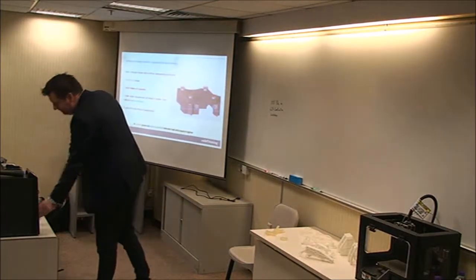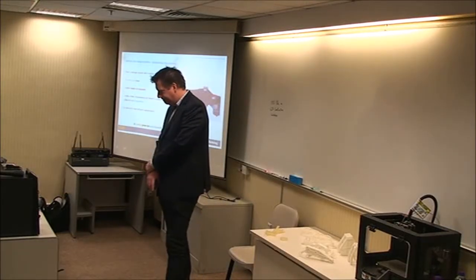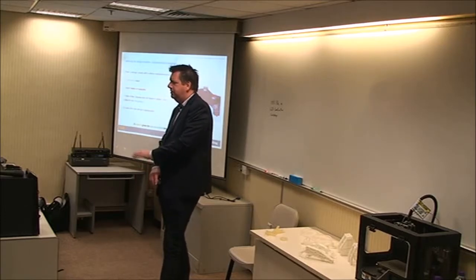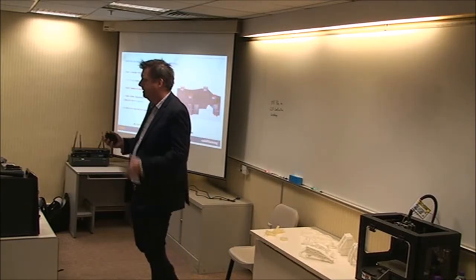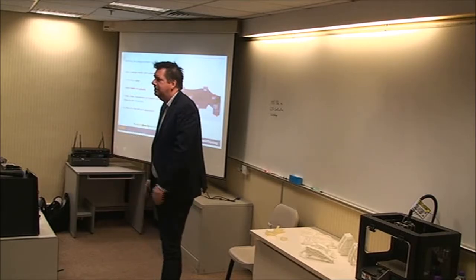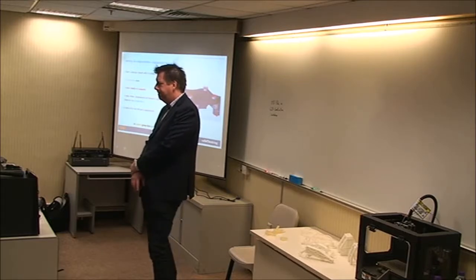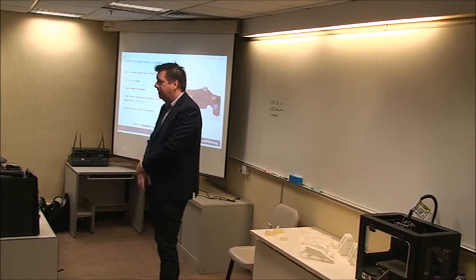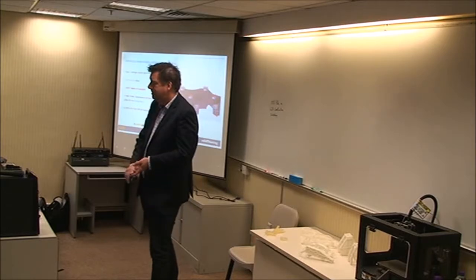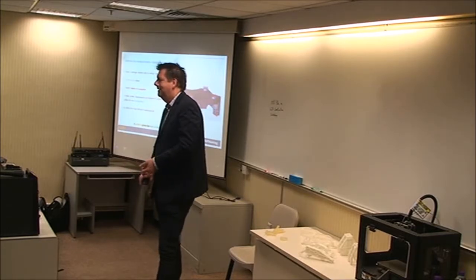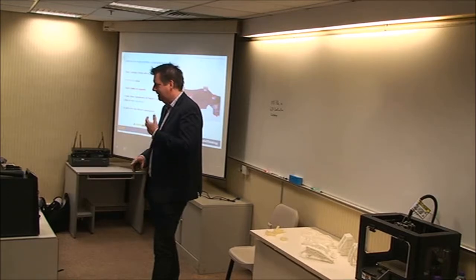Armin showed lots of these little circle of life photos where you start with your design space and work around to get your final result. To me, there are just 2 or 3 underlying concepts. The first one is, given a design volume, the maximum space you can play with, which you can see in brown, you can put manufacturing constraints on that, symmetry, draw direction, or not, because you'll get a more optimum design. Then you've got non-design areas, where you're going to have loads go on. If it's a bridge, it'll be where the cars go on the bridge, or where it attaches. You need to know your loads. You need to know where it's going to be supported. And then you need to really understand the responses that you need to control: displacement, frequency, mass.